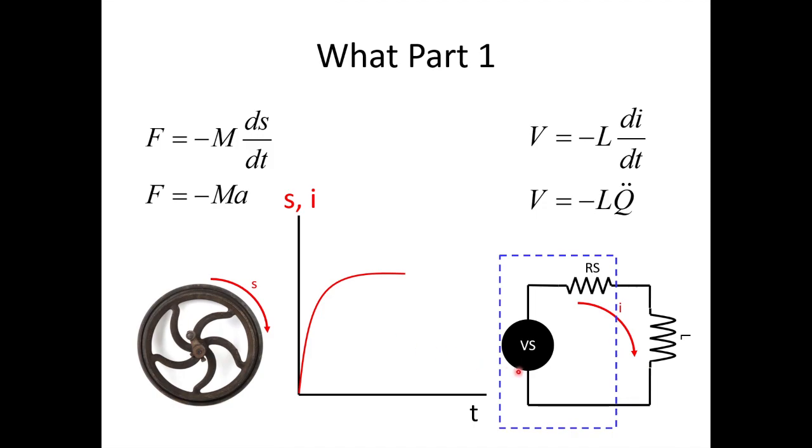Okay, and so the same thing with an inductor. Here's the inductor, and you apply a voltage source to the inductor. The minute the current in the inductor starts moving, starts accelerating, that's what this is, the change in current, you get an opposing voltage that opposes the applied voltage, and it reduces or retards the ability to get the current moving through the inductor. But again, over time, that's going to break down, and eventually the current is going to start increasing to the point where it's going to saturate.